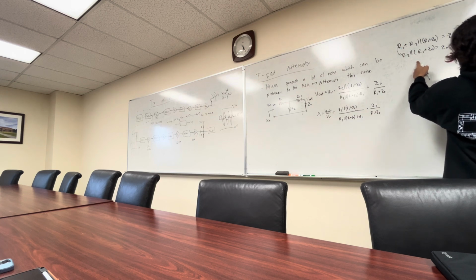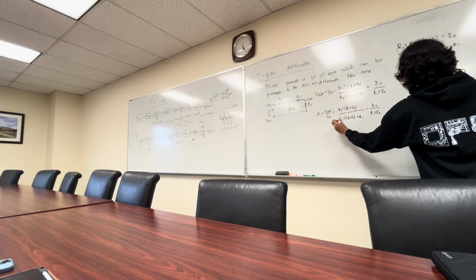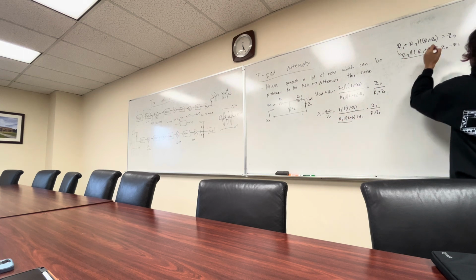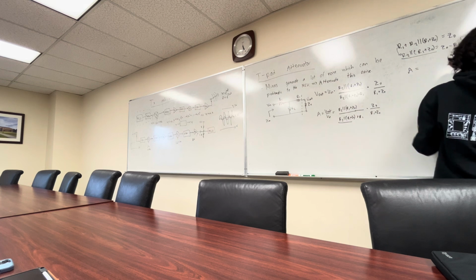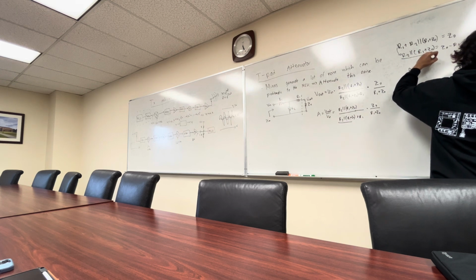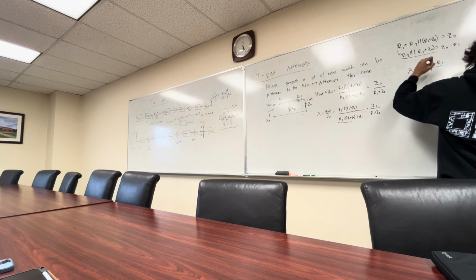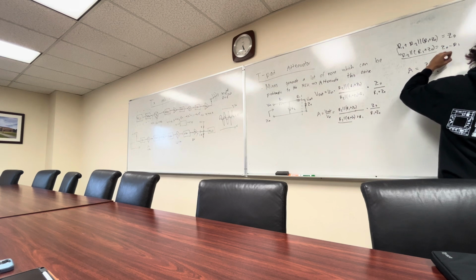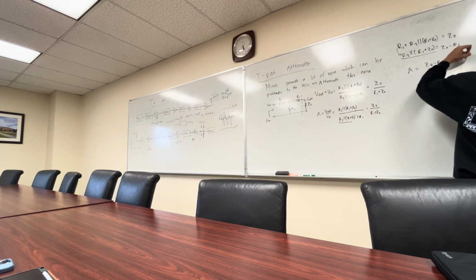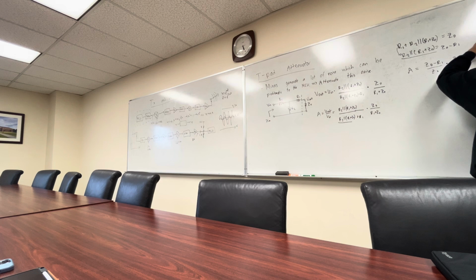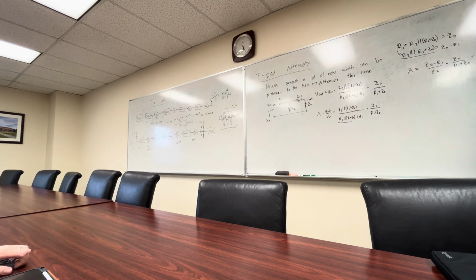And if we plug this in over here, our gain is equal to (Z0 minus R1) over Z0 times Z0 over (R1 plus Z0). So we get this for our gain, so that our gain is effectively independent of R2.